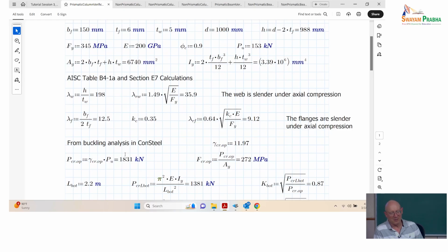So for anything that's a plate that has an h over tw larger than 131, if you plug it in, you're going to be at 0.35. Anything with an h over tw less than 131, then the stockier the plate, kc of the web increases. So that's representing here what sort of restraint or destabilizing effect you can get on the flange from your web.